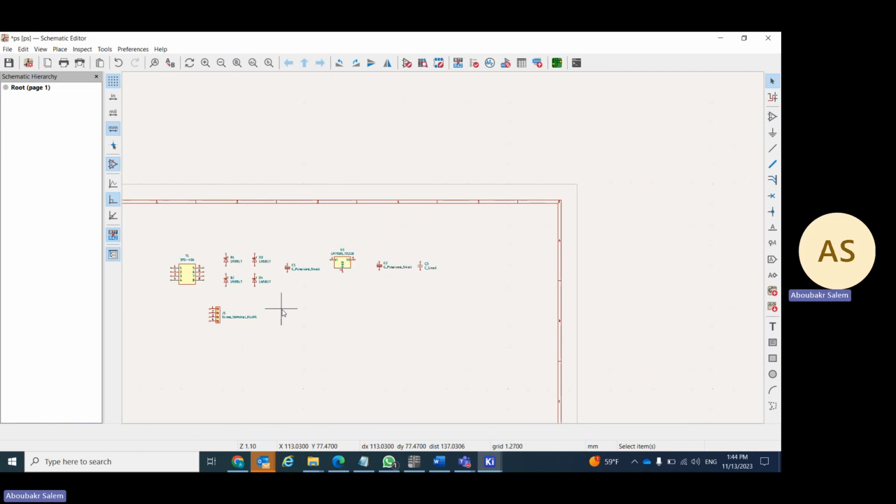Yes, pins or screws, it's up to you. Screws are better for high power, but high power means how much distance you have between your terminals. So for high power, guys, we have a relation between volt and distance between terminals. You know that 1 kilovolt is sufficient to break down or ionize air within 1 centimeter.